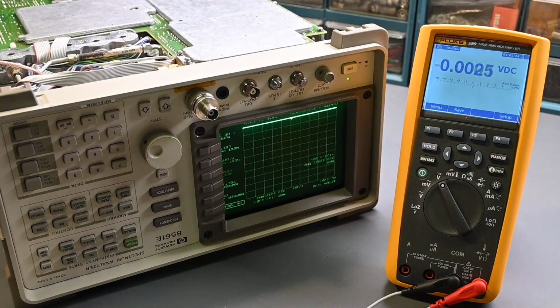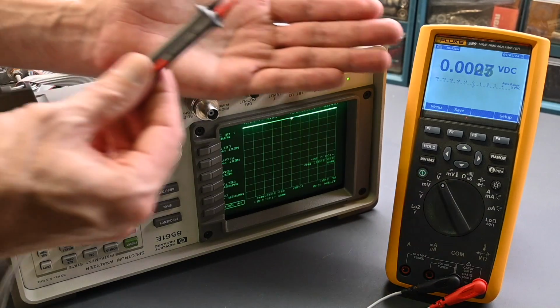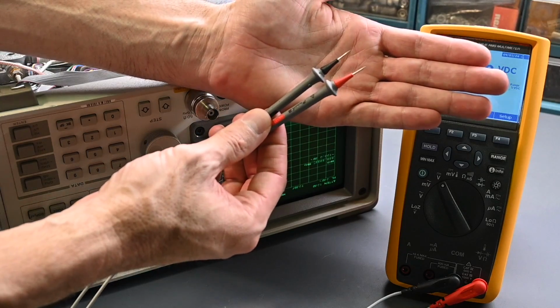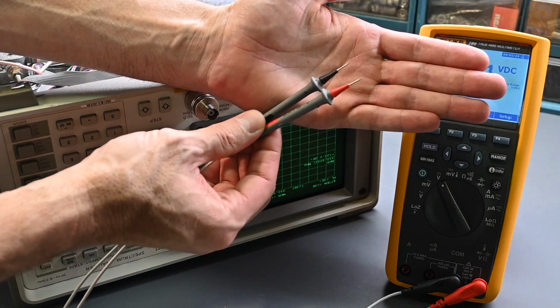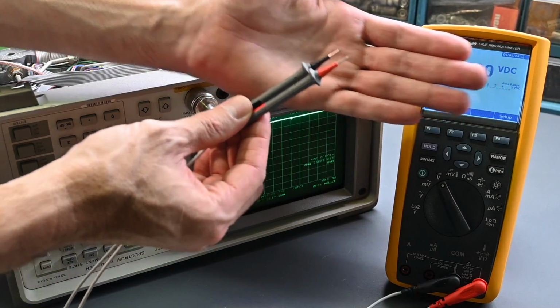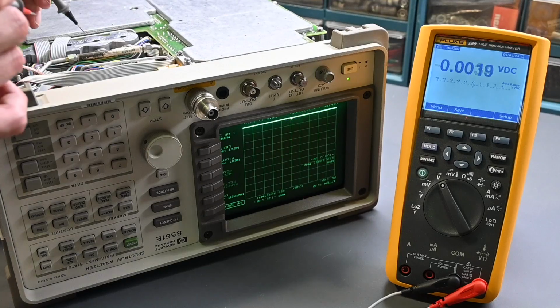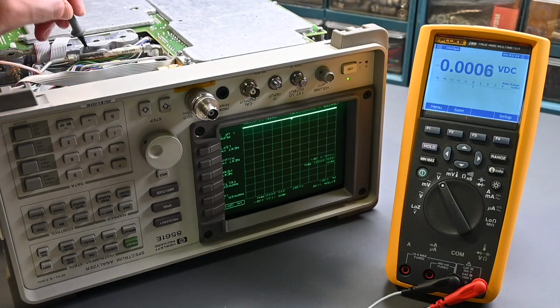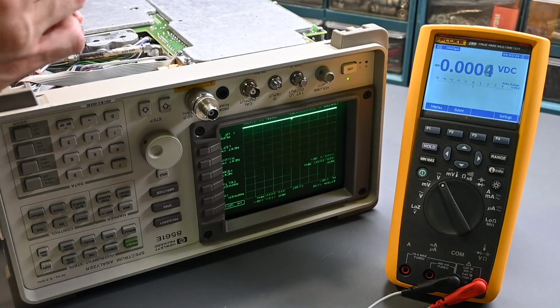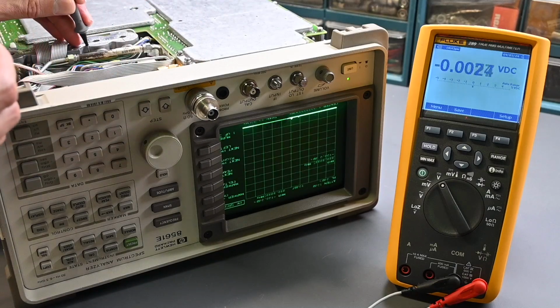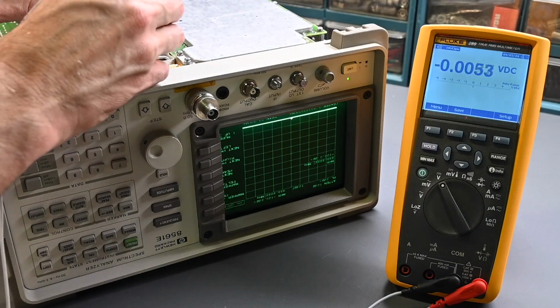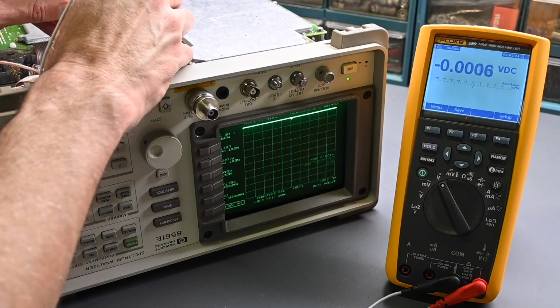Alright, let's see if the correct voltage is being applied to the RF switch. So it should be between negative 9 and negative 10 volts DC. Now I have these probes with extremely sharp and small needle point tips on them. So those work very well for reaching very small components and hard to access locations. And I think I can use these to reach right down alongside the wire where it attaches to the top of the A10 assembly and take a voltage reading there. Otherwise I've got to track it back over to the circuit board and take the reading on the board. So I think I can reach it this way.